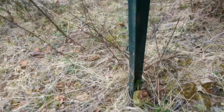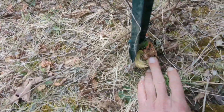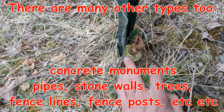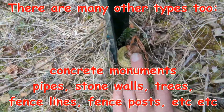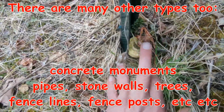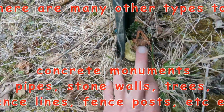Otherwise, what we're always looking for are re-rods like this. They'll be 1/2 inch to 3/4 to 1 inch iron bars, typically re-rod, and sometimes they'll be labeled. They'll almost always be flagged, and you'll notice that this is set at a bit of an angle. That's because we set the stake and then we set the top of that stake within 0.01 feet. That's about 1/4 inch, and we can hold that across a 100,000 foot distance.